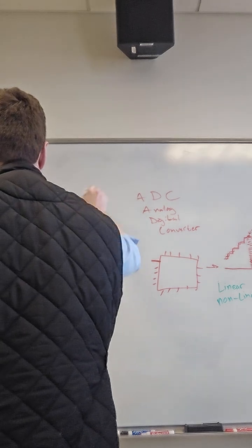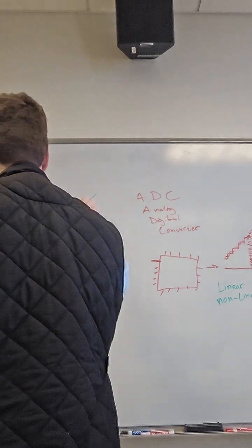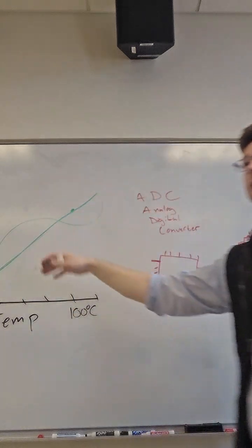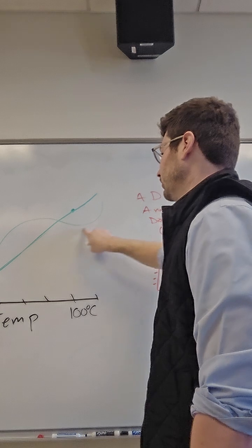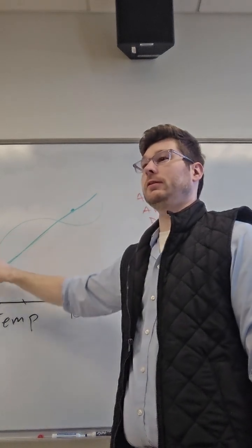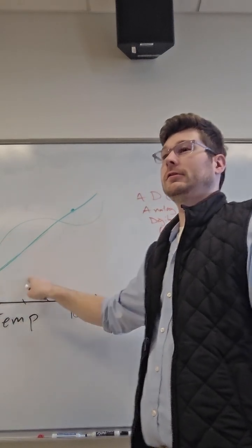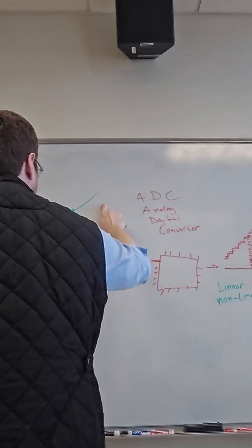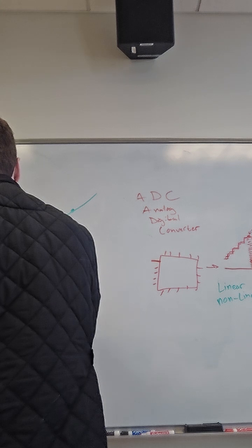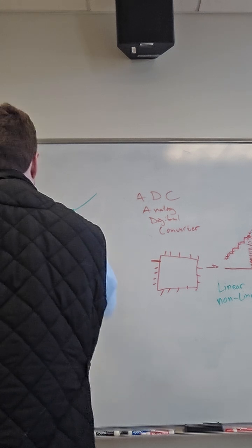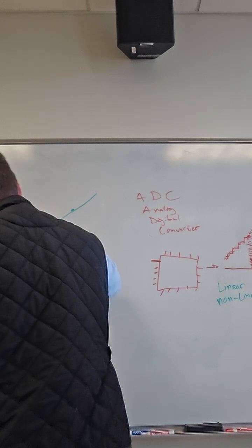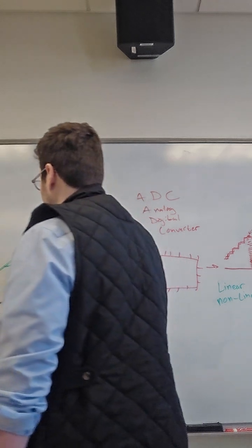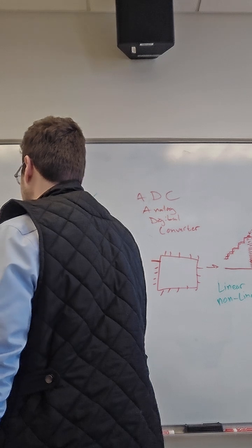You'll have this weird curve, and so a straight y equals mx plus b won't get you a good calibration. You would have to have a complex curve that you could fit to this curve and then look up essentially at every point and correct for it. Anyway, once we have our calibration curve, we can turn our unit into temperature. We're essentially saying for each step of temperature, how much is that in change of voltage?